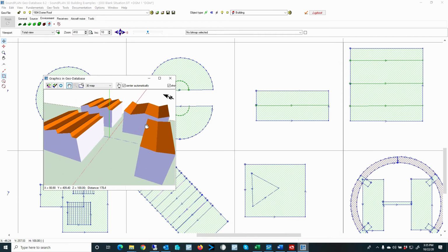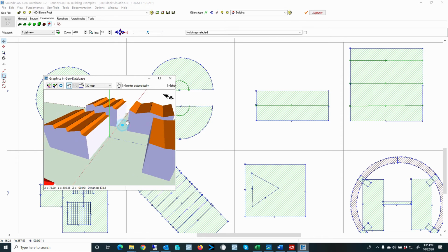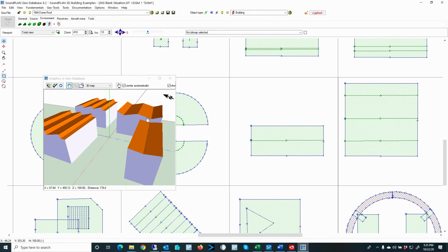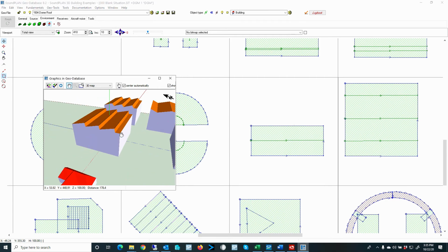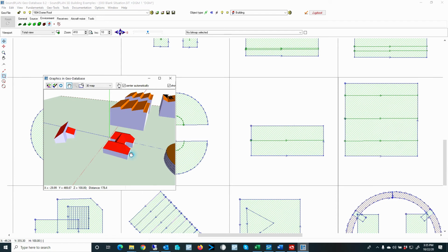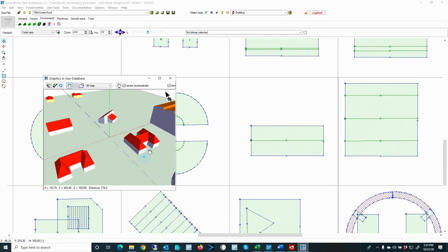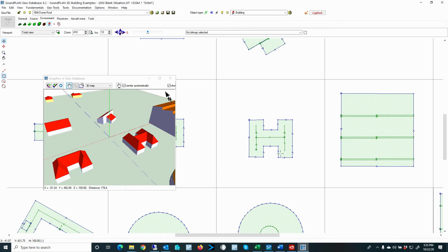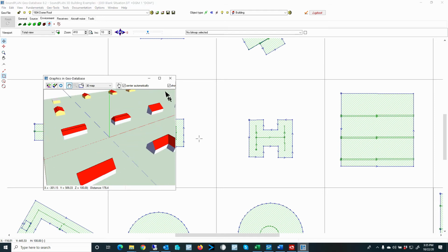So here are all kinds of different ways of how you can assign the roof lines by just defining different ridge lines inside the roof area. So with different elevations you can get this pattern or this shed pattern. And then here again we have also some other roof structures here that are gabled right here.